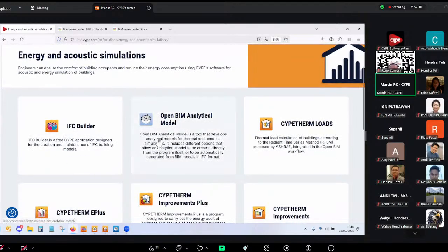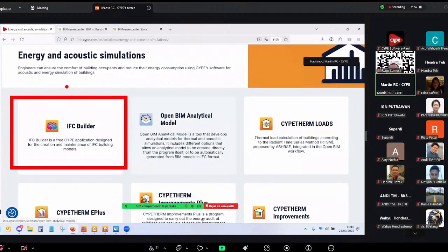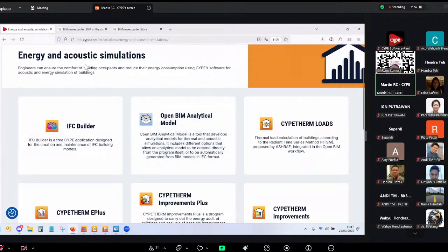There's another option, right? The other option is that we have a BIM model that comes from somewhere else. If what we have is 2Ds of a building, like DWGs or 2D plans of a building, you can simply import those 2D plans into the IFC Builder and model our building there. And if it is a regular geometry building, if it's not geometrically complex, and if it's suitable for modeling floor by floor, and if we just have the 2D, we can just go from 2D to BIM for free by using this tool, right? IFC Builder. And we are having the information of adjacencies and edges, right?